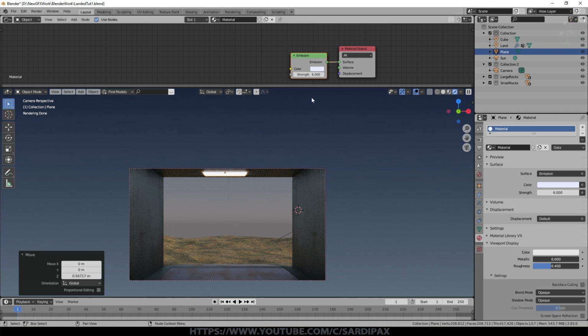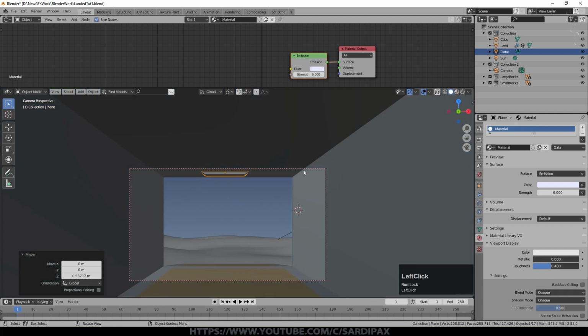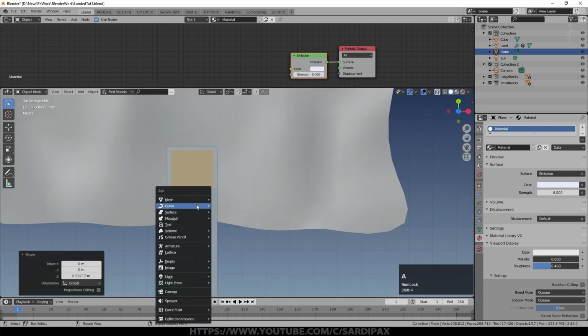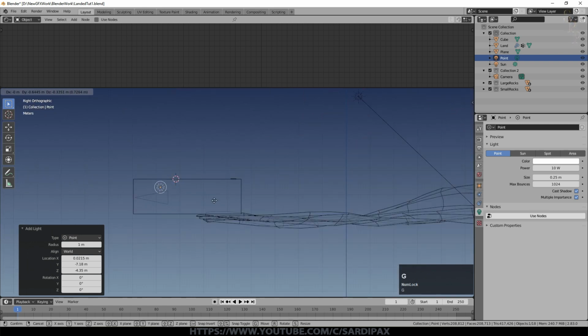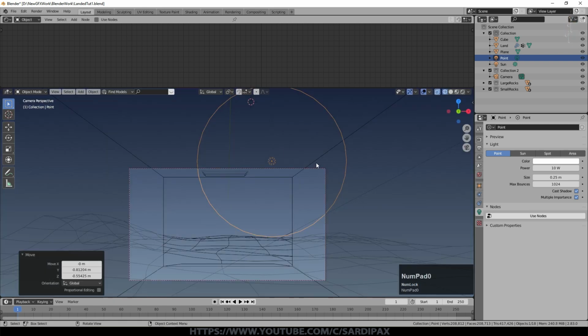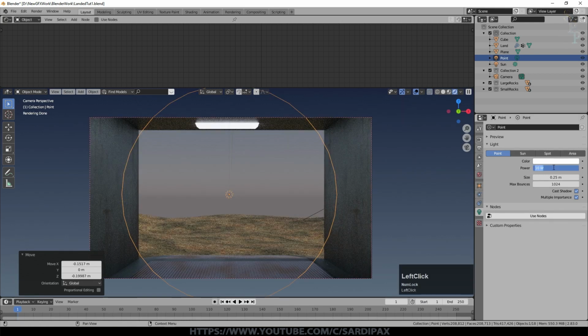You can see we're now getting a bit of extra light, which is helping us to see this material a little better. And what I actually did as well, go to clay view for a moment, is I added a point light as well behind the camera effectively, although it's not visible in the scene anyway, just to really add a bit more light into the scene inside the ship. So if I set that to off, we're not seeing a great deal from it at the moment there. So perhaps somewhere slightly less than that. We'll put that at 50 for the moment.